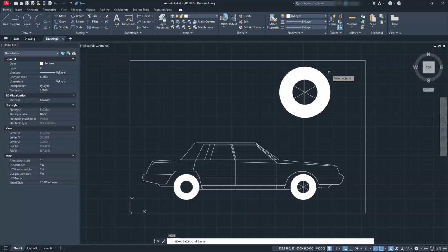and I'm not going to put any dimensions on this or do any of the other stuff. I know in my other videos I go through that a lot, but if I'm strictly using everything in model space, remember, and I hate to sound like a broken record, try to keep your main view here. This view, this scale is going to be set to that 1 inch equals a foot. Okay, anything else that I use off of that, this dimensional one, I'm going to adjust the scale on this.